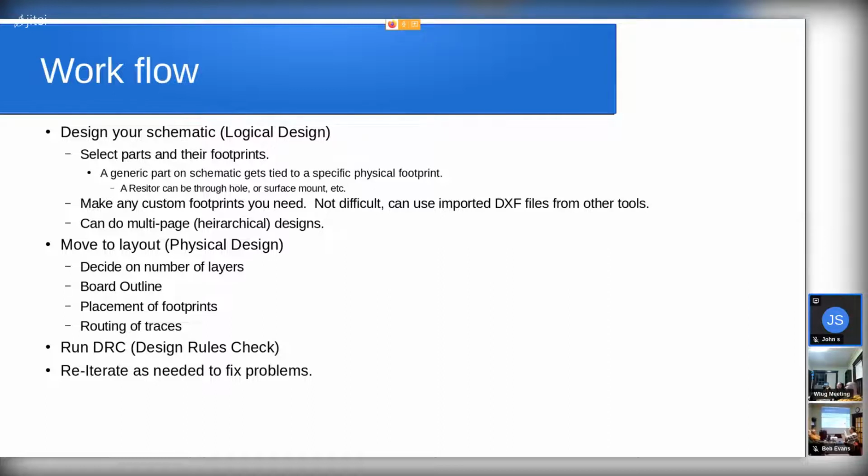You'll sometimes see it where they're running along, and then suddenly it'll make a squiggle. I noticed that KiCAD has it where you can pick one and say make it squiggly, and I think that's so you can have a little bit of a delay. Yeah. So if you're going around a curve, this has a longer path. You might have to put a squiggle in this one if they have to be the same time delay.